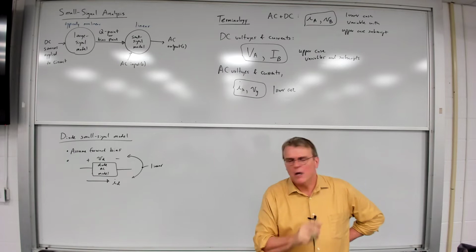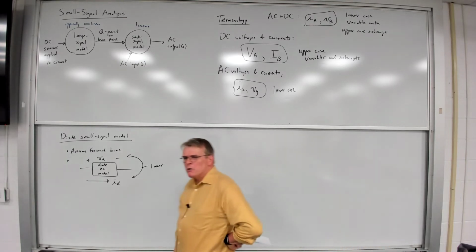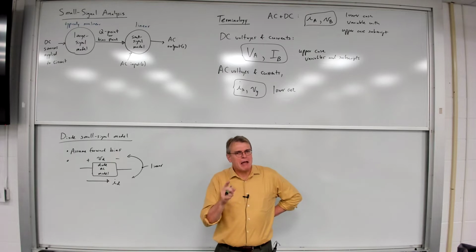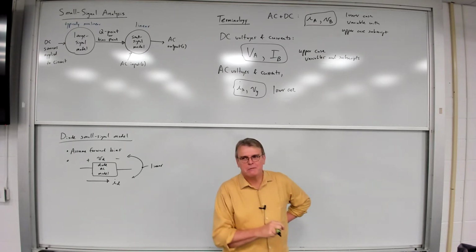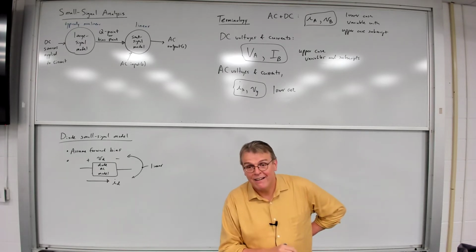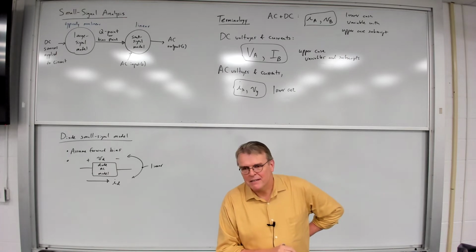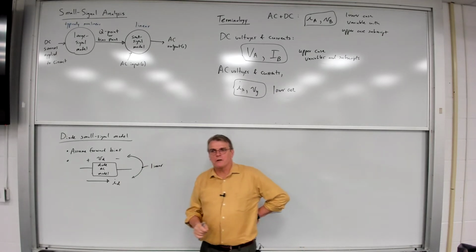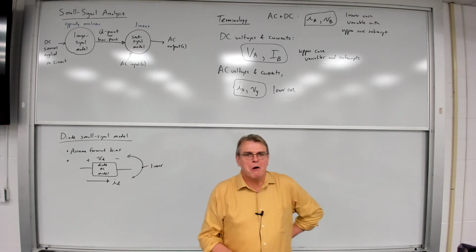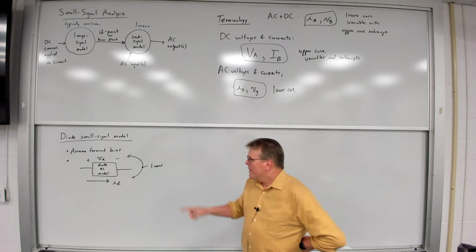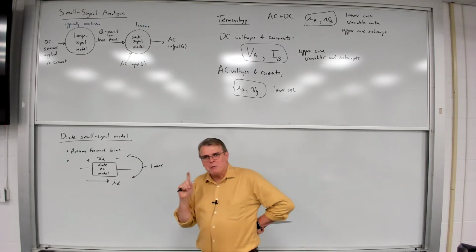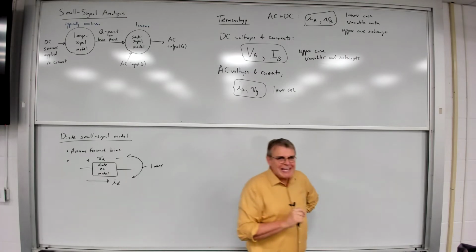It's 2 terminals. What did we learn about in Circuits 1 that was an element that had those properties? What element had those properties? Resistor did, yeah. A resistor, right? Doesn't a resistor have a linear relationship between voltage and current? Yeah, sure, absolutely. Ohm's law, remember that. So it would seem that a good small signal model for a diode is going to be a resistor.